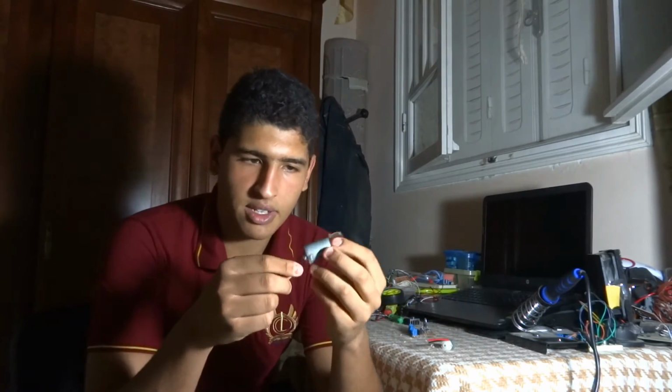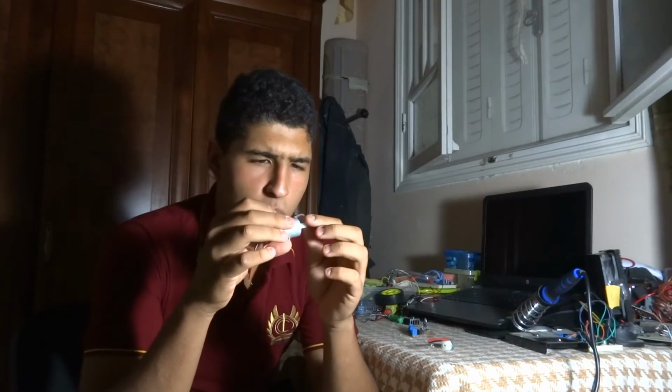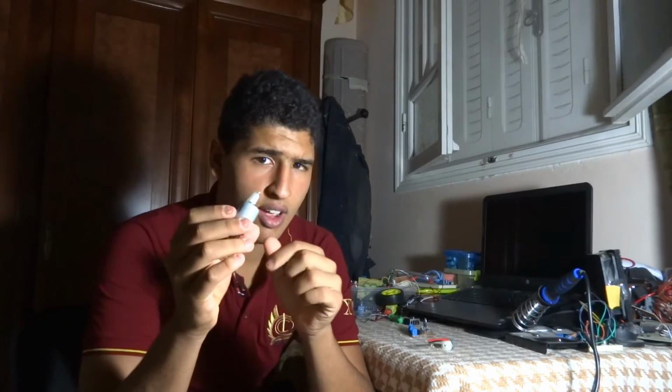I can drive it with my L293D. But this motor actually draws around 1.7 amps, or around 5, I don't know, but it's actually more than 1 amp, so I cannot drive it with the L293D. Well, I can, but it will not work at full potential. So first, check your voltage, how much you're going to give it. If it's more than 36 volts, you need to use the L298N. Second, check the current that your motor draws,